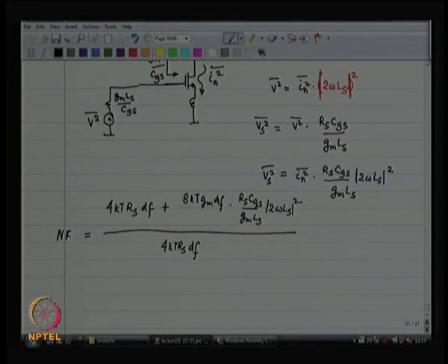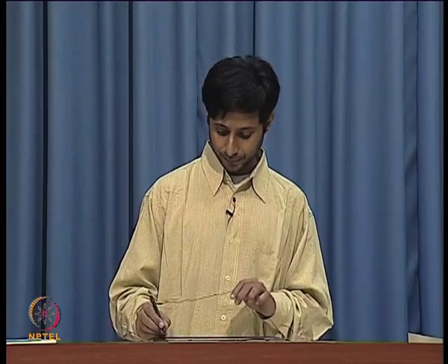The simplified understanding of what is going on is to operate at the match frequency. At the match frequency, if you look at the source looking back from the gate of the MOSFET, you are just going to see the same resistance that you are seeing when you look into the gate of the MOSFET, right. Of course, I have done some approximations here.